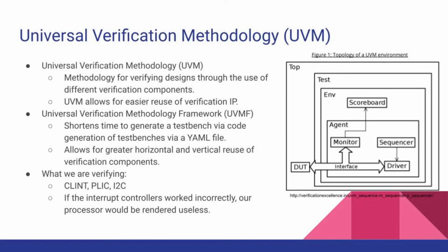The Universal Verification Methodology, or UVM subteam, is a subteam primarily composed of computer engineers whose focus is using UVM in order to write System Verilog test benches that can be used to test SoCET designs. UVM uses random test vectors in order to simulate the device under test, using a set of standardized components including a sequencer, driver, monitor, predictor, and scoreboard. The advantage of using UVM is that the standard components mean that they can more easily be reused, allowing test bench generation time to be shorter, and the creation of additional test benches to be easier.